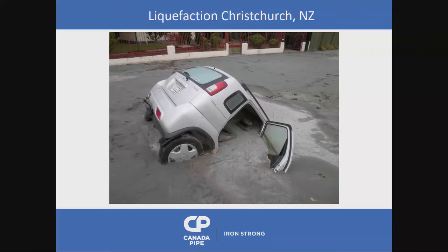So anybody that's an operator out there will know that if they install PVC pipe, they need backfill. They need pressure against the pipe to hold on to that pipe, to keep it structurally sound so it can pump water. What happens if that trench is gone, like in this situation right here? It's gone. The pipe is gone. There is no pipe anymore when you're talking about this kind of effect.